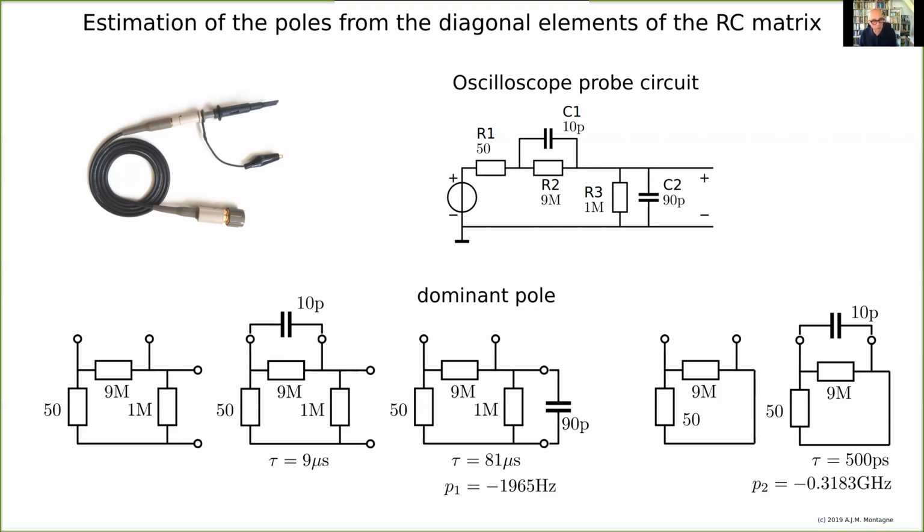So this is the method that we are doing. We are taking the capacitors and inductors out. In this case, the capacitors. Then we build up the resistor network. We then one by one replace the capacitors, look for the time constant with the largest value. That is what we call the dominant pole. Short this pole and do this again for the next one, and again and again. So if you have 10 capacitors, you make 10 different circuits, and every time there's one more shorted. This is the way it works.